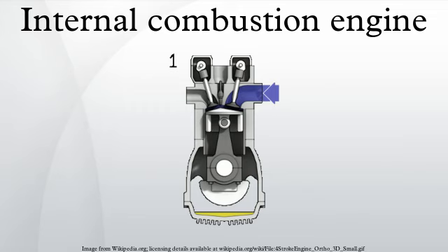As the piston proceeds downward, another port is opened, the fuel-air intake port. Oil mixtures come from the carburetor, where it was mixed, to rest in an adjacent fuel chamber. When the piston moves further down and the cylinder doesn't have any more gases, fuel mixture starts to flow to the combustion chamber and the second process of fuel compression starts. The design carefully considers the point that the fuel-air mixture should not mix with the exhaust, therefore the processes of fuel injection and exhausting are synchronized to avoid that concern.